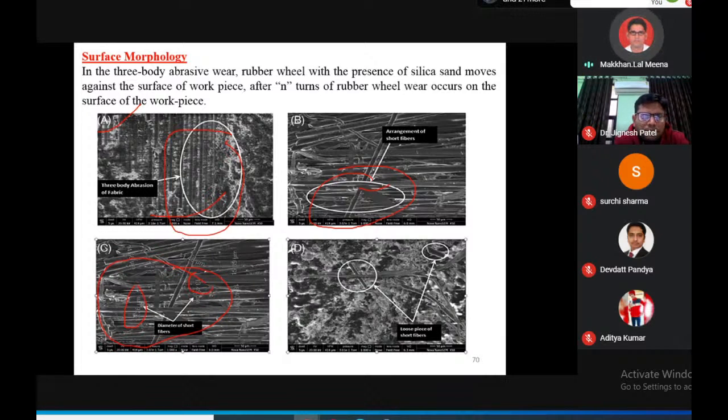The diameter variation of glass fiber is also shown in figure C, and due to better bonding characteristics of basalt fiber and epoxy, there is low matrix wear and less fiber damage in the reinforced composites. Fiber breakage of glass fiber composites has increased considerably at 20 Newton load. You can see this in figure D.